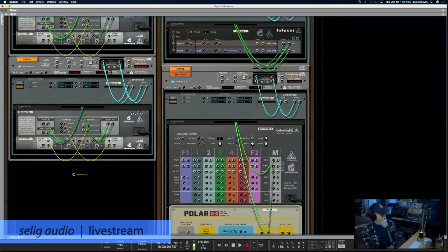When you understand signal flow, it manifests itself as you're hearing something and you're trying to figure out why you're hearing what you're hearing, and you're trying to find where it's happening. That's when understanding the signal flow comes in very handy, because normally when you troubleshoot, you start at one end of the signal flow or the signal path, and you track it through and say, I got it here, I got it here, I don't got it here. So between that point and the point before is where the problem is. So that's signal routing deep dive.